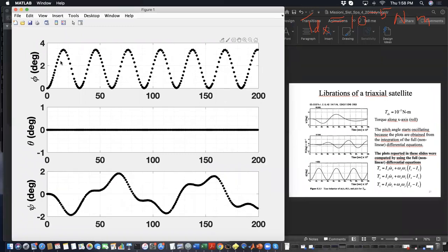So you need to activate your actuators in order to provide a 0 error, a 0 control error. So what we are going to see next week, we are going to start with the actuators that are applied to this passive stabilization, so wheel dampers and magnetotorquers. Those actuators enable to dump this oscillatory behavior. And afterwards, we are going to see the other two main actuators. They are the thrusters and the reaction wheels that will provide the possibility to control the attitude in 3 dimensions.